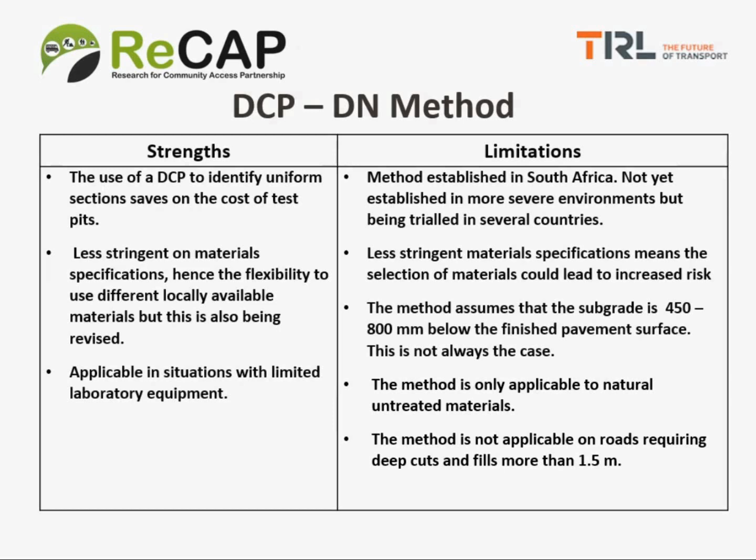And the method is not applicable on roads that require deep cuts and fills of more than 1.5 meters, because clearly the DCP is a measurement system of limited depth. The handle, I think 1 meter is the normal, but there can be extensions up to about 1.5 meters, but obviously it's not applicable if you need more than that.